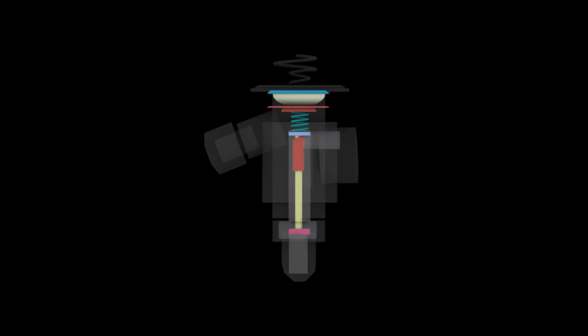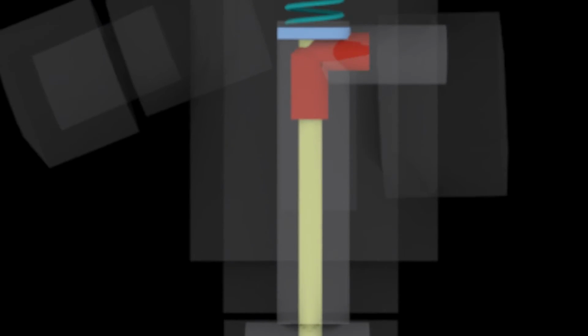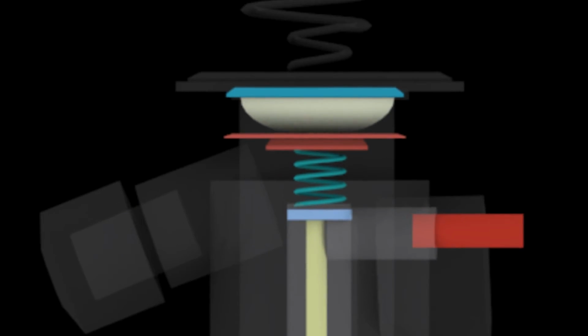After some time, when the temperature inside the refrigerator falls to the desired value, the mercury will contract. The pressure drop above the diaphragm causes the spring to lift up the push pin and close the valve. The refrigerant will stop flowing and at some point after the valve closes, the compressor will cut off.